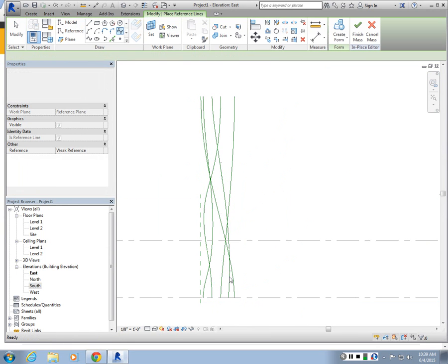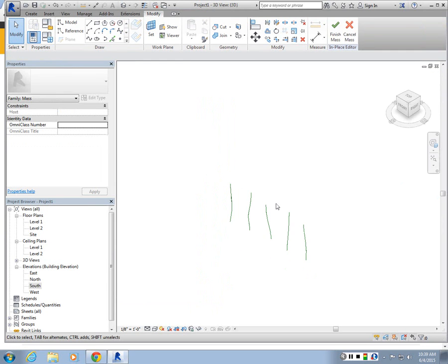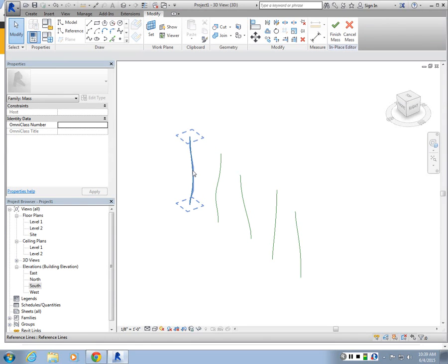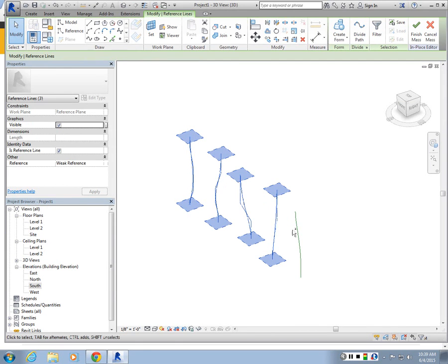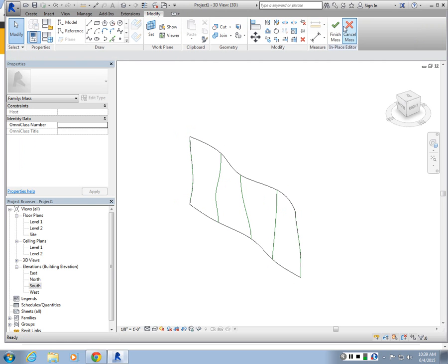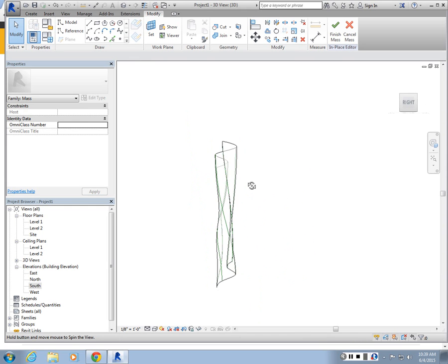And that's the last profile. So if I look in 3D, I have 5 profiles lined up. And what do I do? I choose all the 5. Choose create form. Boom. I got a lofted surface. So it could be like a skin, basically. Right, something like that.